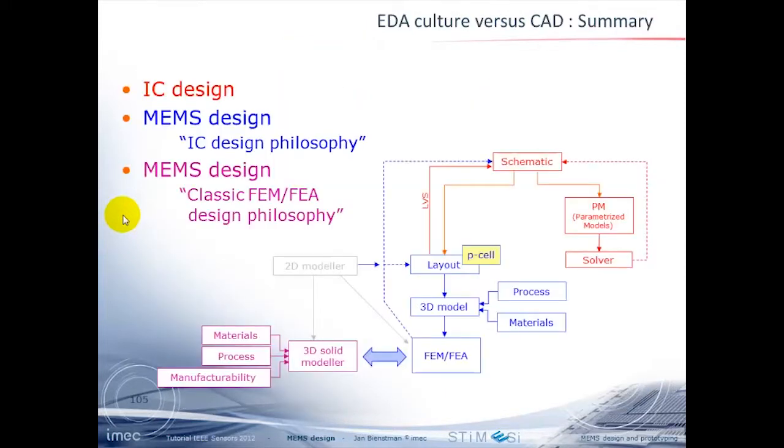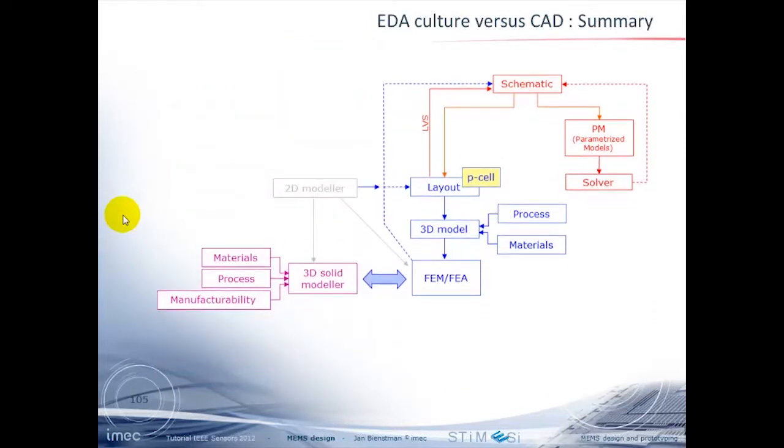Okay, I'll quickly go over this. So, to summarize, if you are in the phase of a top-down approach, your process is already known. For example, you're working on a fixed technology where there's a design kit available, within Europractice or any other, let's say a multi-project wafer service, you have CIC in Taiwan, you have CMP in Grenoble in France. Then, of course, you have this design kit, and you can start with layout, make a 3D model, and you can do it in that way.